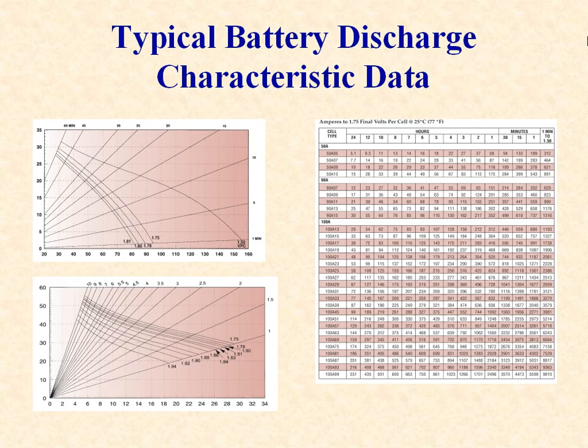Battery discharge data may be in graphs and/or in tables and applies to a specific cell design. For the definition of a lead-acid battery into the PTW library, we need data in a per-positive plate format. It can be in the form of a discharge curve, like those shown here, as RT curves or as KT curves. Graphical data is usually given on a per-positive plate basis. Tabular data is typically given for a series of specific cell sizes. Thus, to use the tabular data, it is necessary to divide by the number of positive plates to get per-positive plate data.